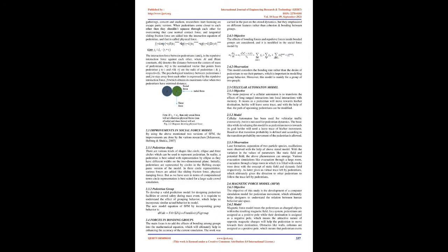Literature review. Social force model. According to Helbing and Molnar, 1995, a pedestrian is used to the situations which he/she generally encounters during movement, and they have the ability to perceive the situations, and according to different situations, he/she will react. That's why they have defined the pedestrian behavior into the equation of motion. The interaction between the environment and pedestrian are described with forces. Pedestrians are driven by three forces, namely, desired force, interaction force between pedestrians i and j, and interaction force between pedestrian i and the walls.